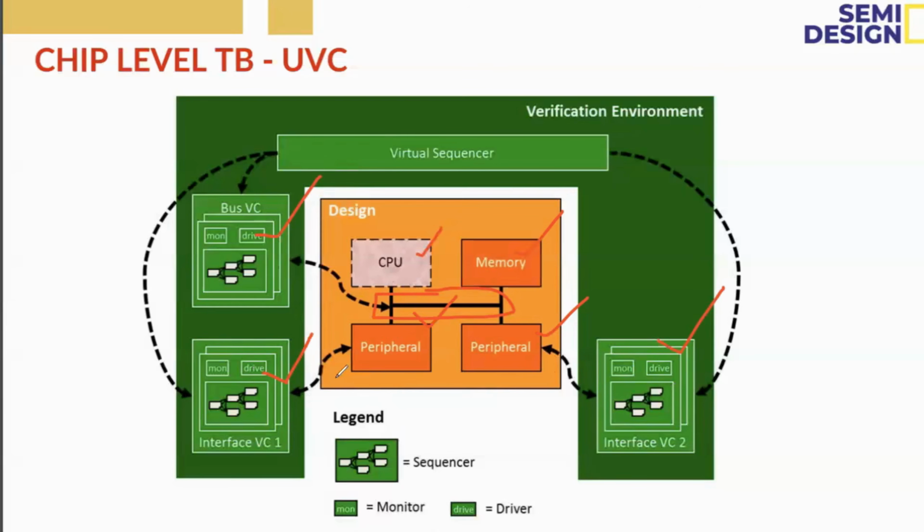From all these UVCs, we have taken sequences to the virtual sequencer, and as a user, our work is mainly how we are creating our own scoreboard, how we are connecting the scoreboard to the monitor, and how we are writing the virtual sequences. That is our main work as a SOC verification engineer.